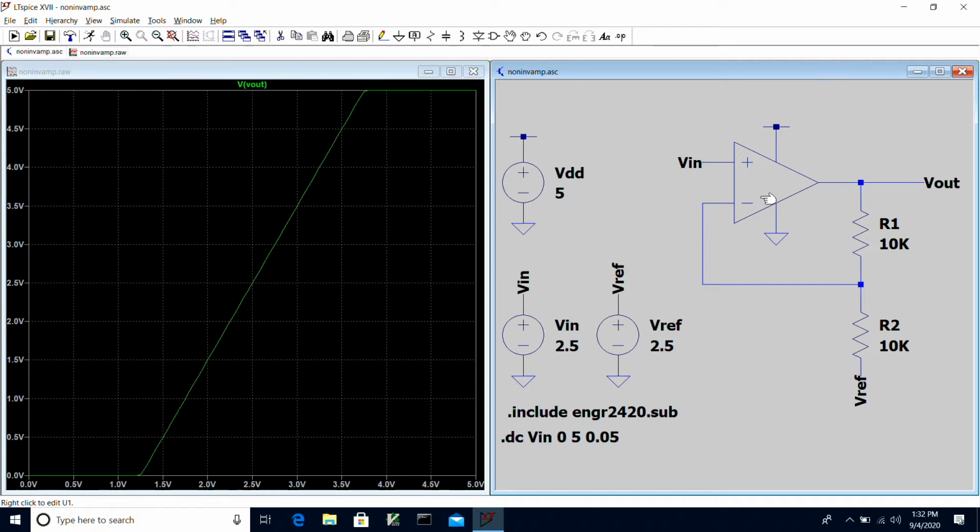And so if the voltage is not stuck at one of the rails in the steady state, that must mean that the two inputs are at the same point. So the op amp will basically be maintaining this inverting input at whatever Vin happens to be. And so the node here at the middle of this two-way voltage divider between Vout and Vref is basically Vin.